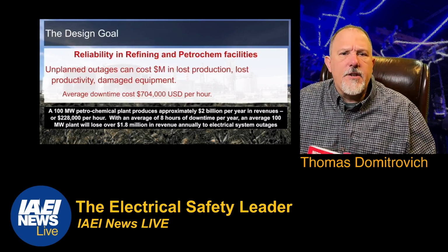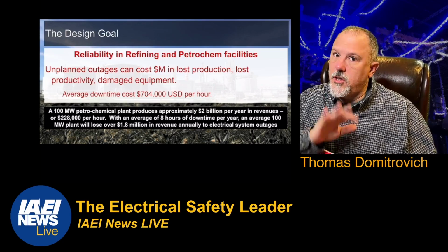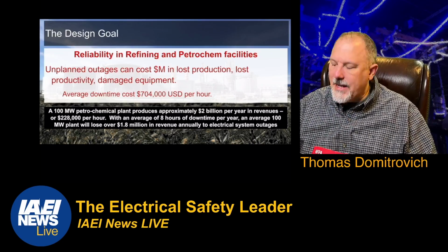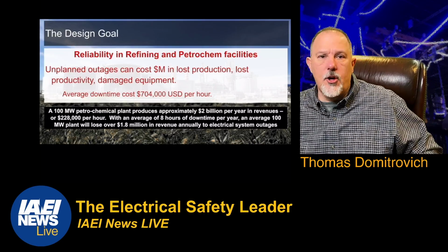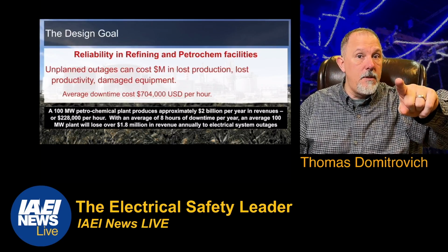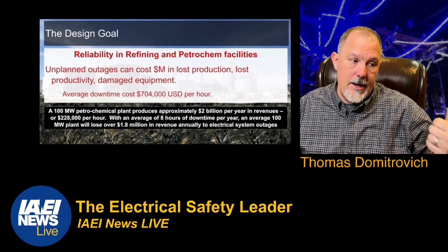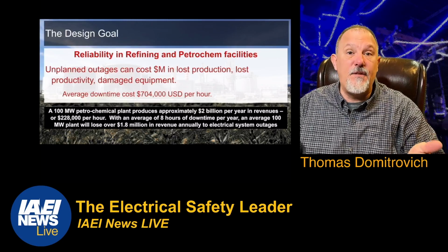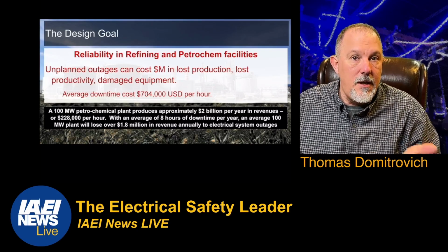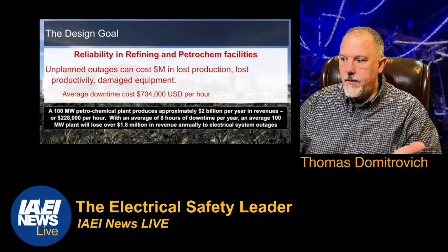Arc flash reduction is 240.87, only starts at 1200 amps and above. Why there? Why can't you put that technology elsewhere? Ground fault protection of equipment, only 1000 amps and above. And Tom, only on service equipment. And now in the 2023 code cycle, they went to feeders, 1000 amps and above. Why would I put that anywhere lower in the system if I'm not required to?